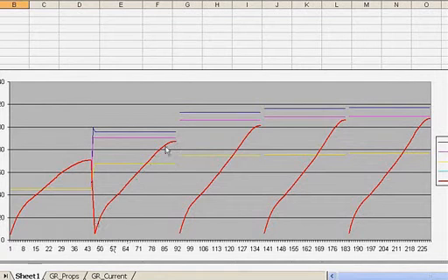It's the magnetic field intensity for a given voltage. So we're fixing the voltage on the winding of the core, and we take what we get with the current that flows. And you can see that as the core gets hotter, we are getting some increases there and some nonlinearity as we're going further and further out on the BH curve.